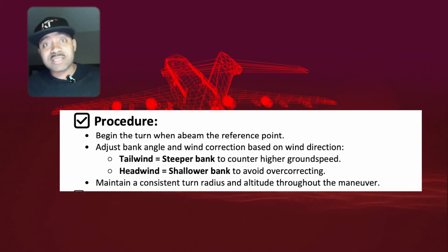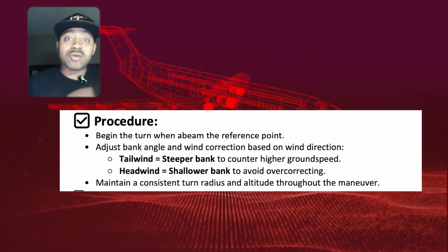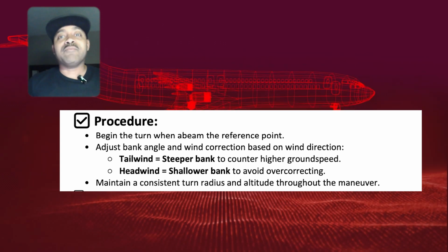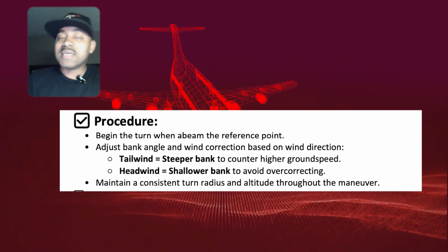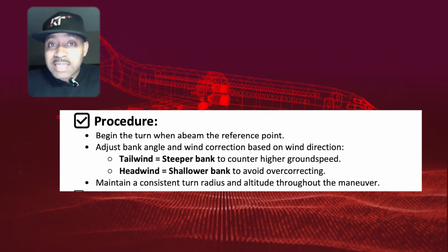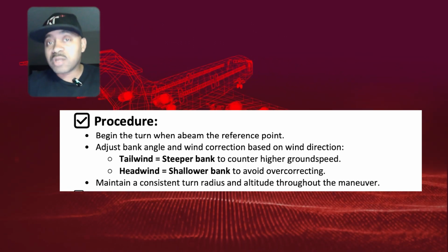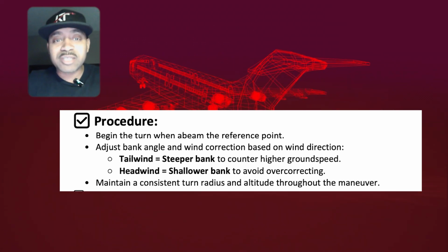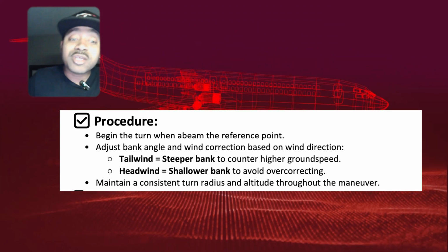One way I like to do this as a technique is, as I'm entering the point, I look at 4 points that are around the point that I'm flying around and make sure that as I'm going through the turn that I'm flying over each of those points. Now, not saying that you should just fly it like that, but that gives you some good reference points to let you know if you're too close in, if you're too far out, how's your bank doing. It's kind of to help you check yourself out, make sure you're doing good while you're doing your turns around a point.